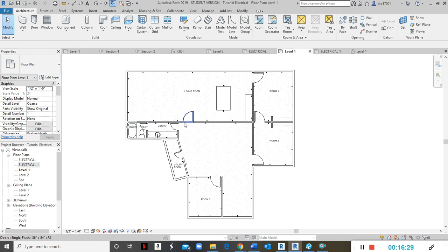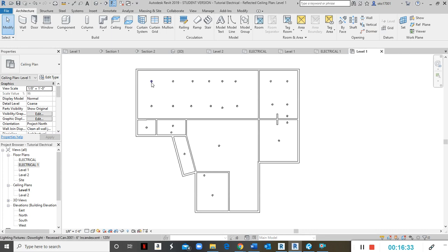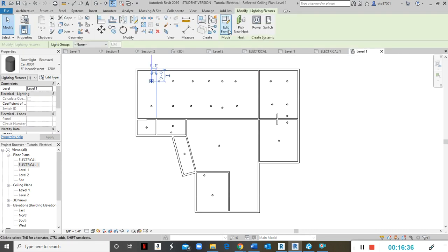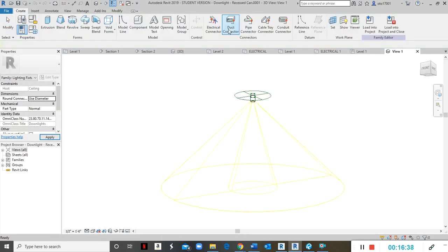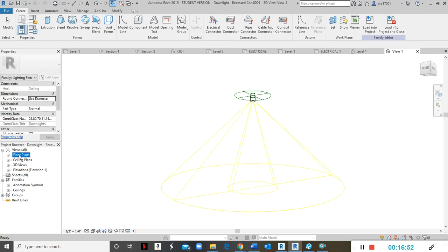To make them show here, you come here, sorry, to ceiling, click on one of these, edit family. Over here, you can click on views. There we go, elevation.